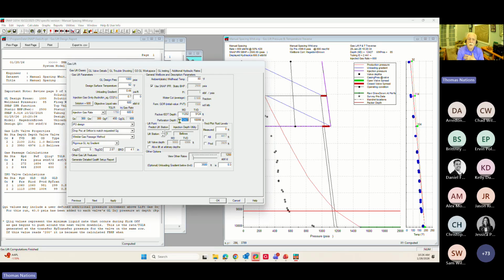All right. And then this little toggle here is going to allow us to set our lift point at different depths. For example, I turned it to 2 and it moved it up a whole one. It depends on how you've got your system set up. You can count from top to bottom or bottom to top, it's your preference. What I've found over time is that if you're running conventional gas lift mandrels in your well, then you're going to count from bottom up, because number 1 is the first one in the hole when you're running your completion.